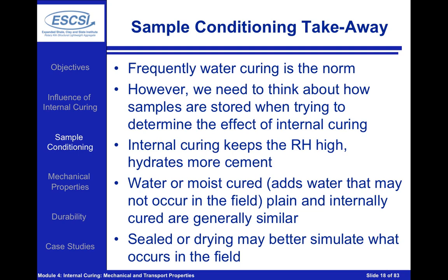However, when we look at concretes that may be sealed or concretes that may be drying, the supposition here is this may actually be closer to what we see in many of the field cases, and here we're going to see a big distinction between the internally cured and the plain concrete because we have that additional water that's helping to hydrate more of the cement, helping to hydrate more of the supplementary cementitious materials. And what we're going to see is that the internal curing is going to get us very close to the case where the samples were water cured.